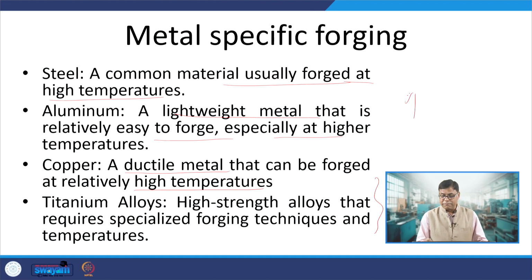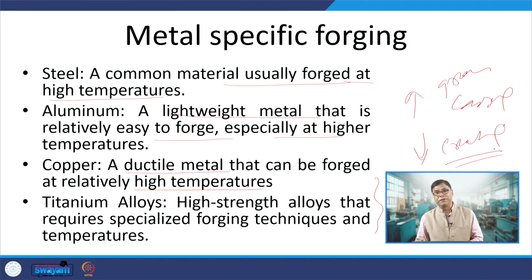What happens if the temperature is too high? It will compromise the properties of the product that will be made due to grain coarsening, and if the temperature is low, then it will increase the cracking tendency due to the limited flowability.